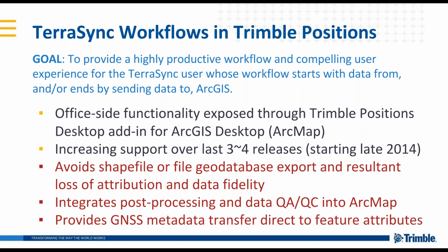And we've done that through this Office side functionality exposed through the Trimble Positions desktop add-in for ArcGIS Desktop. It is for ArcMap. We've gradually increased support for these workflows over the last 3 or 4 releases dating back to late 2014. And fundamentally, the reason it's advantageous is it avoids any shapefile or file geodatabase export and any loss of attribution in the process, or names getting truncated or things like that.